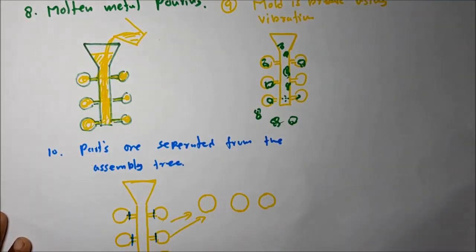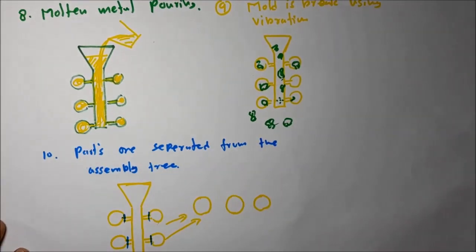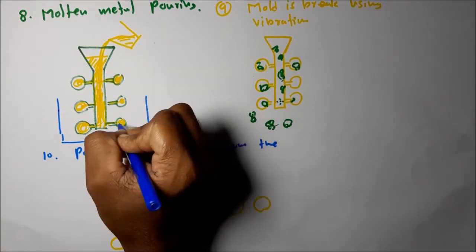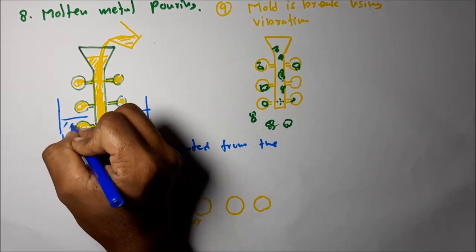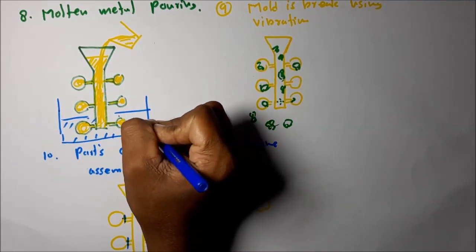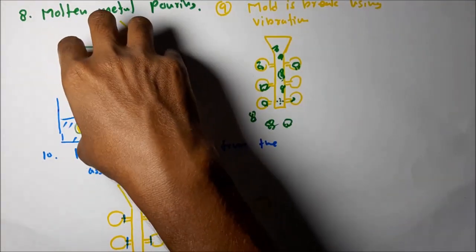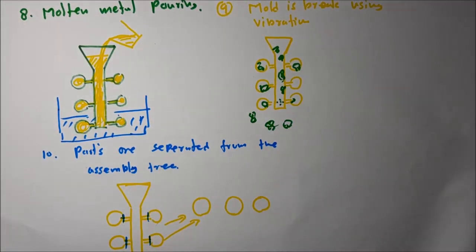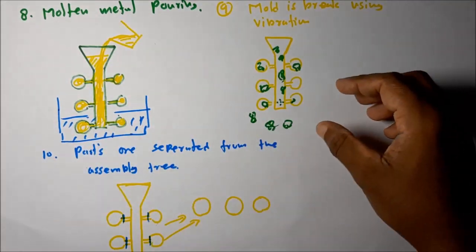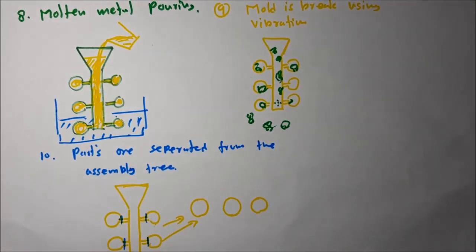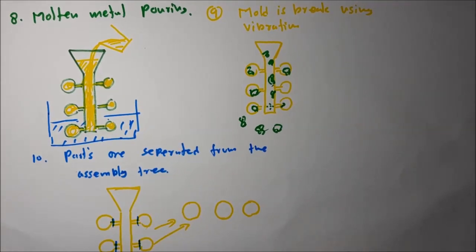Like this. Now sand containers are used to place this in a vertical position. Sand-based containers are used to keep it vertical. Then this mold is ready to pour the molten metal. Then the molten metal is poured. You can see in this pouring that very high pouring temperatures are used.